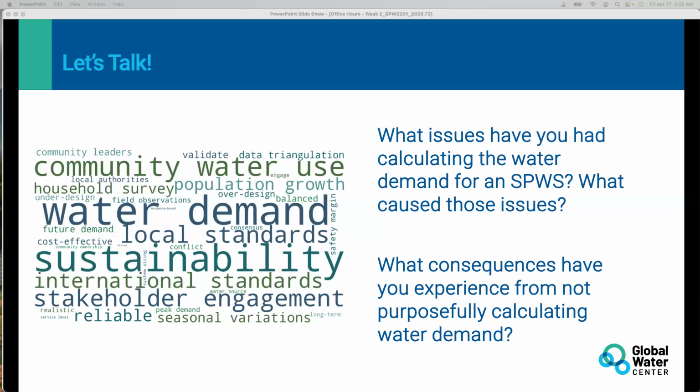The other point I want to stress is that when we design a system with a grid or a gen set, we usually take 1/3 of the maximum demand for the service reservoir construction. But with solar, if it's the only option, we multiply by 2, even the maximum one, to have one day. That will be another challenge we have to encounter from the beginning. So what is the experience from others on this part?